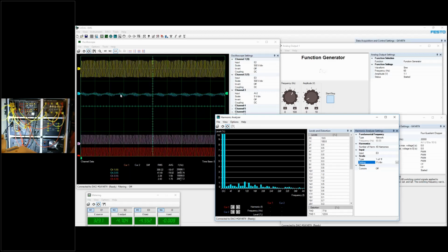It's the noise that is created by the high frequency switching of my transistors here that generate these high level harmonics. So that's why it's important at the output of a circuit like that to have a good filter to get rid of these harmonics, to feed a purer signal to our load.